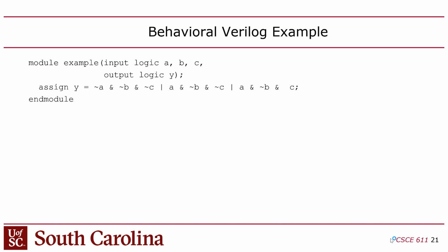The only thing it does enforce is it wants you to declare signals before you use them, which you've seen before in C++. Verilog, for whatever weird, bizarre reason, still enforces that, even though for the most part, order of lines of code doesn't matter. But it still doesn't want you to use a thing and then declare it underneath.